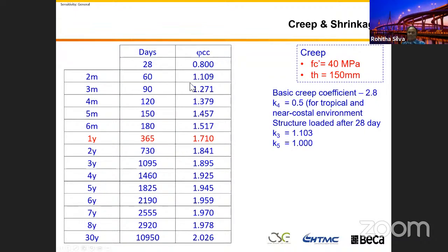This 28 days means I apply the load after 28 days, when I just let the concrete gain its full strength and straight away load it. I calculate the creep factor for 40 MPa concrete in the same environment we discussed, hypothetical thickness 150, in the Sydney area.